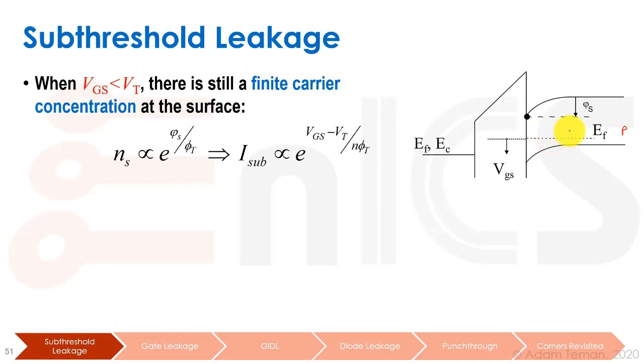Furthermore, as we raise the voltage on the gate, we're actually starting to bend the bands, and as we bend the bands, we start to accumulate more and more charge on the surface. We may not have hit inversion, where the number of minority carriers is the same as the number of majority carriers used to be, but we still have more and more carriers that start to accumulate here as we apply voltage.